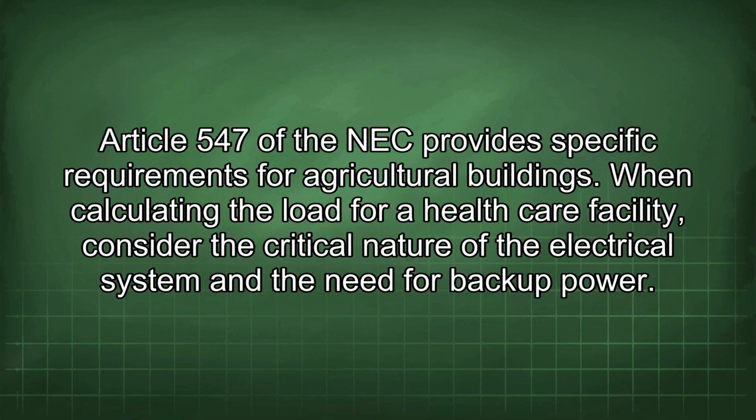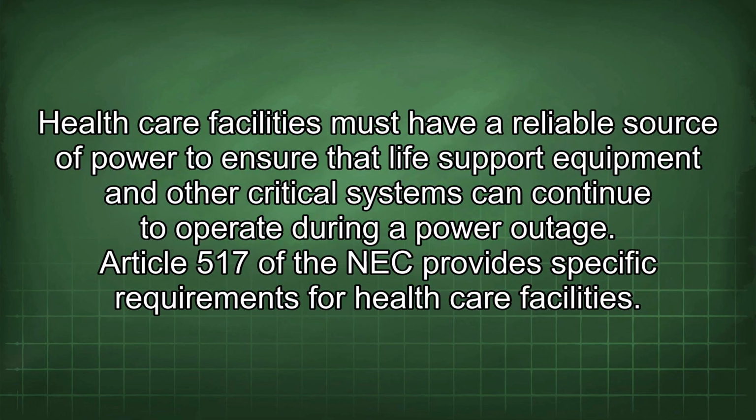When calculating the load for a healthcare facility, consider the critical nature of the electrical system and the need for backup power. Healthcare facilities must have a reliable source of power to ensure that life support equipment and other critical systems can continue to operate during a power outage. Article 517 of the NEC provides specific requirements for healthcare facilities.